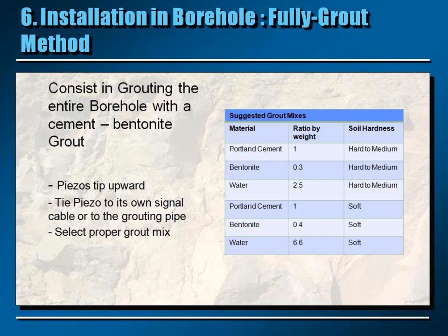The selection of the grout mix is important. As you can see on the table at the right, normally you will try to select a grout mix that will be close to the type of soil that you are in. So for the permeability and the stiffness of the grout, you will try to match those of the soil just around the piezometer.